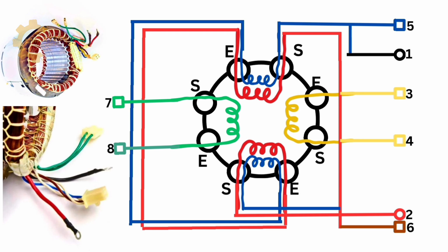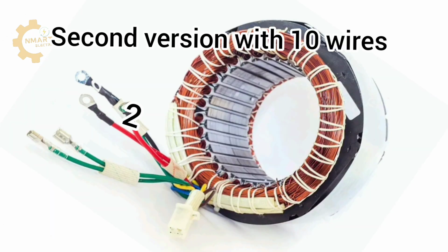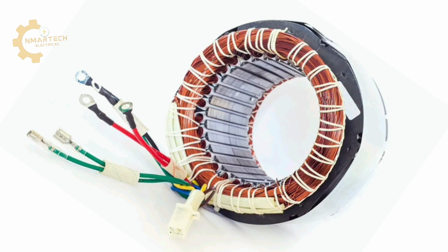A very important one, guys. If you see a stator like this with 10 wires instead of 8, do not panic. These ones accommodate 110 volt loads, just like we see in some countries like United States of America. I'm going to teach you also how the connection is being made in order to get 10 wires instead of 8 wires.